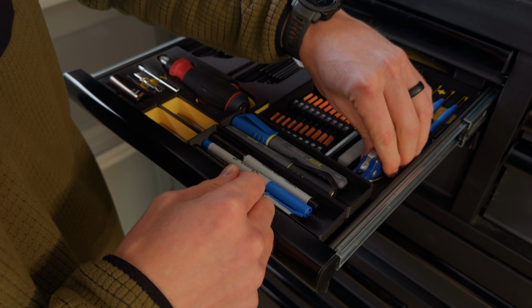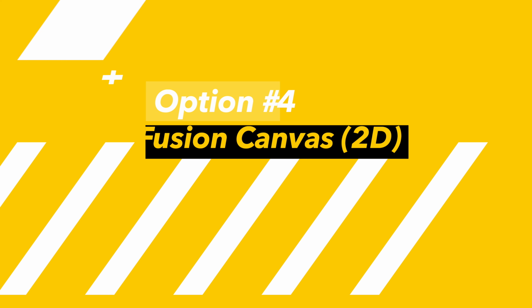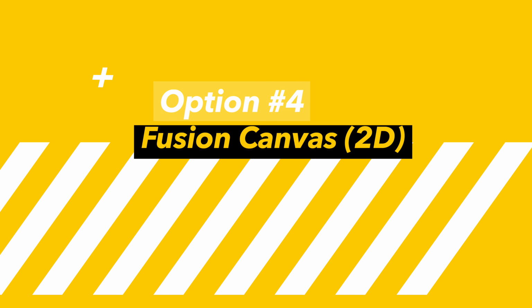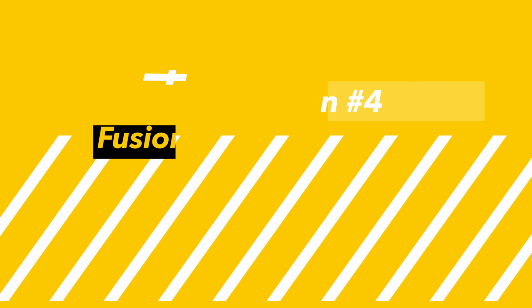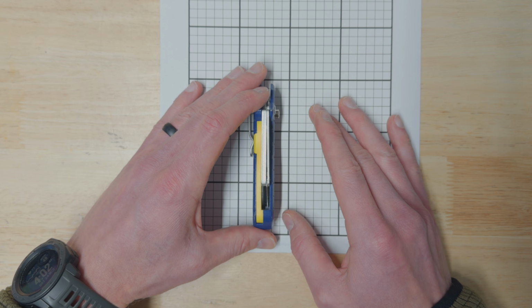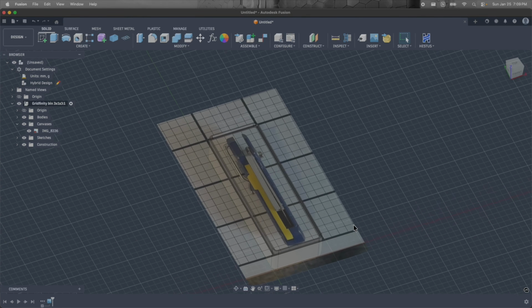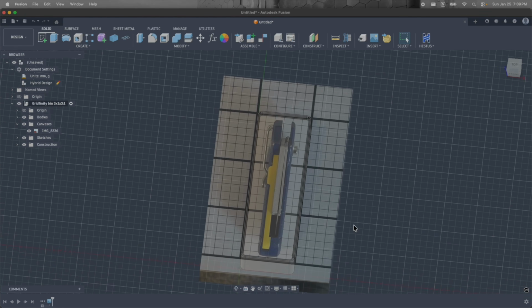And now, let's jump back into customizing shadow boxes for Gridfinity. Now, the easiest way to jump into this again is by taking a picture of your part on the Gridfinity graph paper, because it not only helps you visualize the size of the overall box that you're going to need, but also gives you a great method to calibrate the size of the picture when you bring it into Fusion to help guide your sketch.